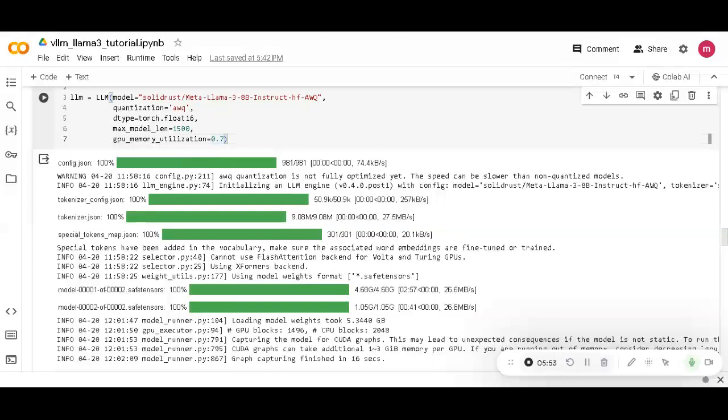You can change that based on your available memory and how much free space you need to perform some other operations or to save some other model. And if you fill this GPU memory to the upper limit, then anytime you can face an out of memory error. So based on your application, decide how much this parameter should be.